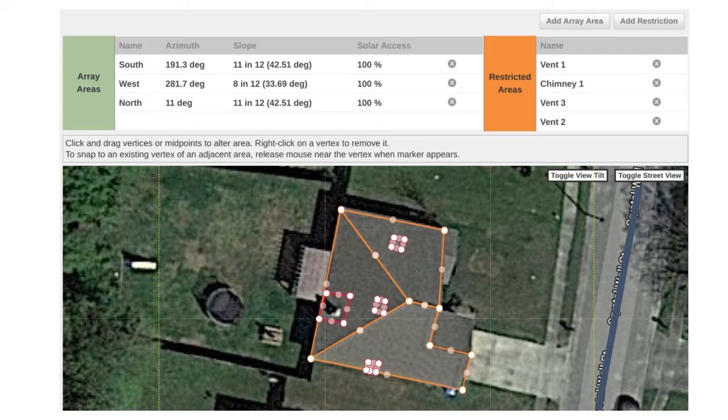So if the array's look is significantly improved by putting a solar panel a little bit closer to that chimney, it may be acceptable so long as the client understands the design decision. In any event, clearance space around the chimney is more important than clearance space around a plumbing vent, and staying clear of these obstacles kind of removes the need for nuance.